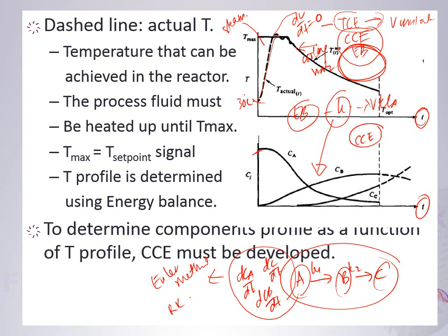Then how do you decide when to stop? How do you decide when to stop? Okay, this graph suggests this is the point, the T optimum. Why? Because at this point you have the least of your CA, the CC is about to pick up, but your CB levels off here and is about to go down. Remember, you want your CB, you don't want too much of CC, because CC is your undesired product. So this is when you have to stop.